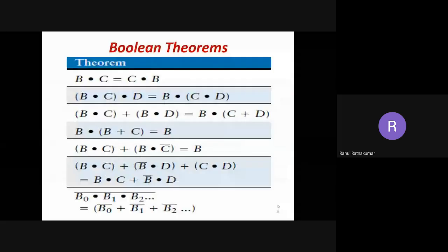One of the important things is these we have all discussed already. You know them already. It's not difficult. And De Morgan's theorems also. B0 into B1 dot B2, etc., all bar. Split the bar, change the sign. Split the bar, and you change AND into OR and OR into AND.